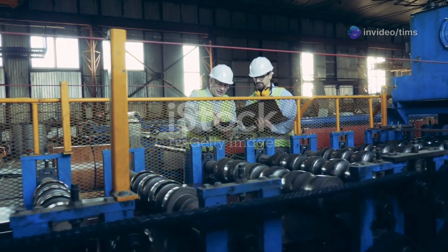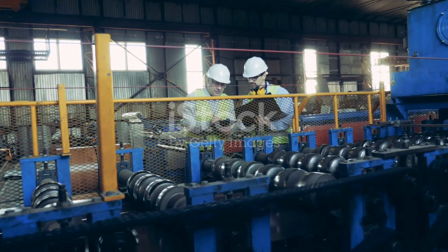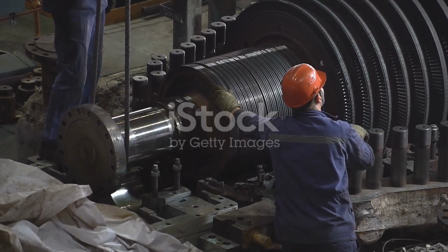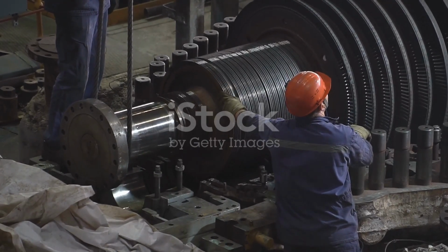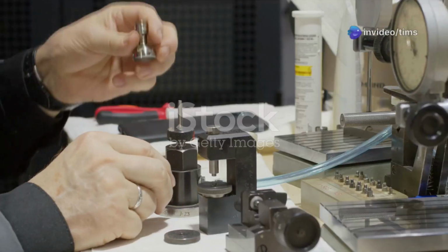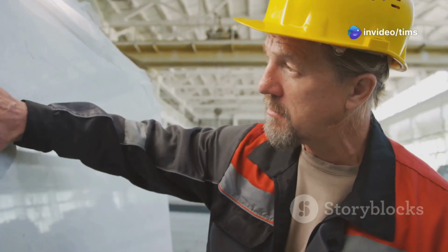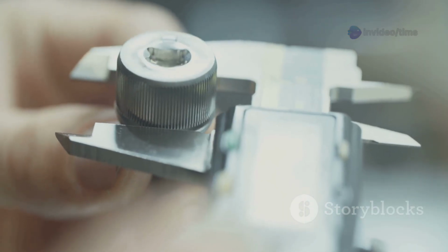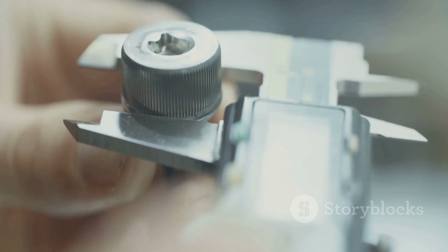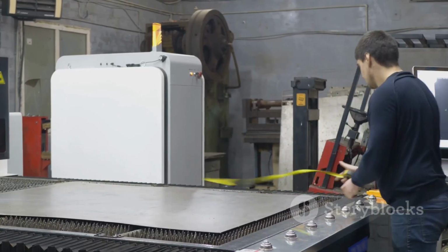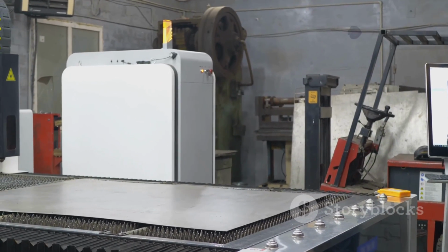Preventing curl defects requires a multi-pronged approach. Regular maintenance of tooling equipment is essential. This includes inspecting dies, rollers, and other components for wear and tear. Quality checks at various stages of production are crucial. This includes inspecting the curl after each forming operation. Early detection of defects allows for timely adjustments to the process.